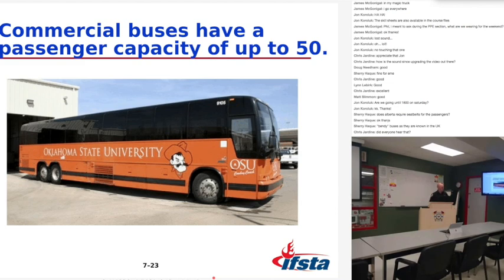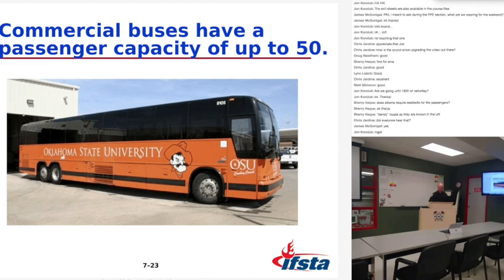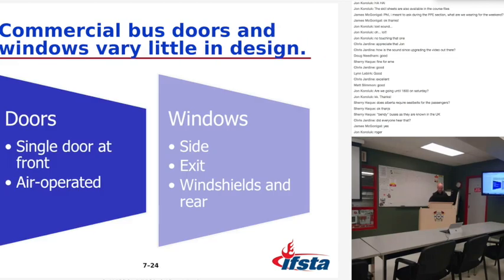Commercial buses. Designed to transport large numbers of people over long distances. May include bathrooms, kitchen, and sleeping areas. Integral construction. Frame covered with sheeting. Panels may not be riveted to structural members. Floors are 1/2 to 3/4 inch plywood covered with a composite rubber or other synthetic covering. So maybe those floors you could go through.